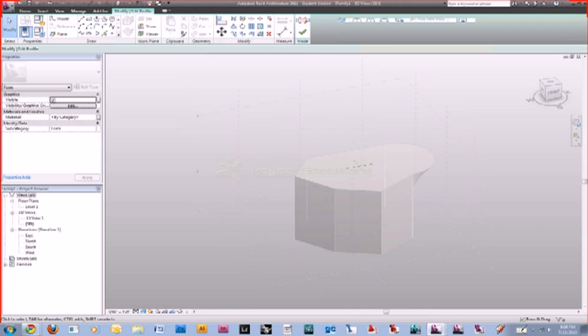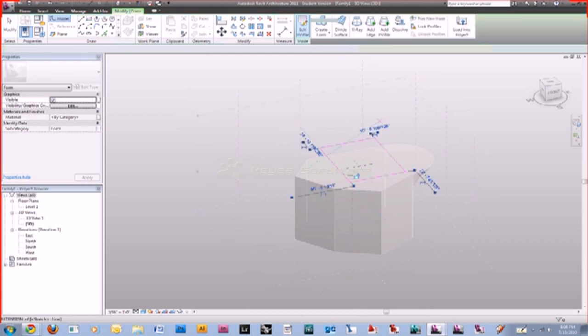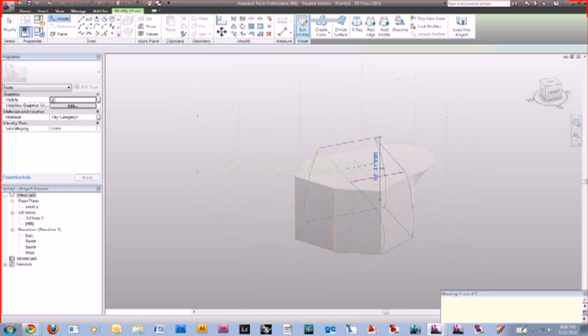If it's a sweep, then you can edit those profiles as well. But you can't really change the way the face looks because that's not really what's defining it. The profiles are. You just have to kind of get yourself to remember that parallel to the plane you drew the object on is a profile, and perpendicular is an edge, so it doesn't have a profile because that profile is being created from geometry clashing together.